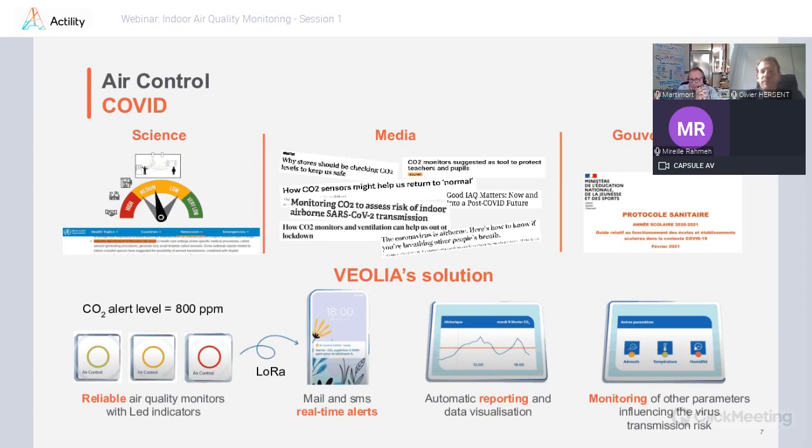And of course, this is in the ideal case. The best place to put the sensor is in the middle of the room, which is almost always not possible. So the choice should be far from any windows or opening doors, at around 1.1 or 1.3 meters, so it will be at the same level as the breathing level of the occupant. And when we have a huge volume, and we need to control the ventilation system using the CO2 level, it's sometimes better to have more than one sensor in huge places.